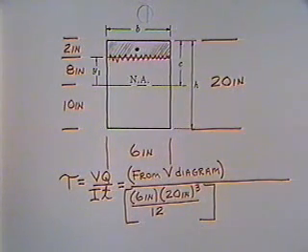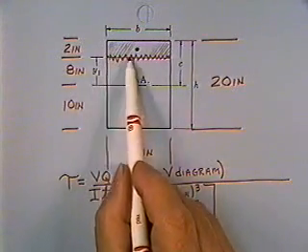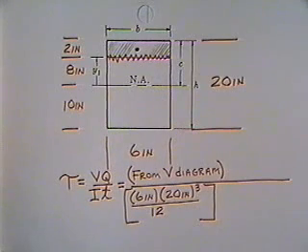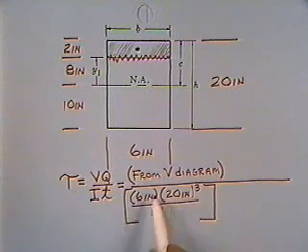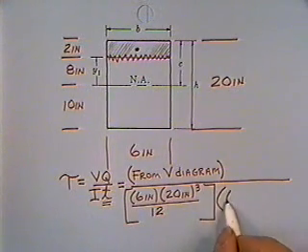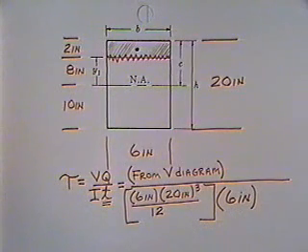When my boss asked me for the stress on this line, I drew a wiggly line on the picture. The length of that wiggly line is T. However long that line is, that's what goes in this slot right here, T. So in our case, it is a 6-inch length. It's how thick the beam is at that level. And the last thing is Q.